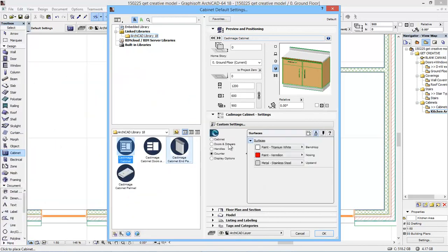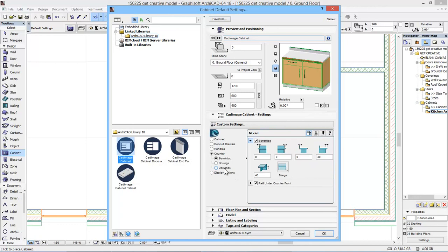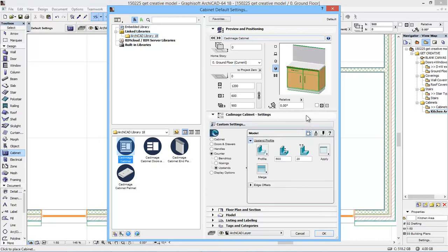Stainless steel, because what I'm actually going to do with the upstand is go back into the parameters for it, and it's currently 100mm. Let's make it 600 above, so this maybe is a splashback for maybe an industrial kitchen or a lab or something like that. Because it's stainless steel, it's unlikely to be 20mm thick. It's probably only going to be about 4 or 5mm thick, and it's probably not going to be radiused, so it's just going to be fitted on the back of here.